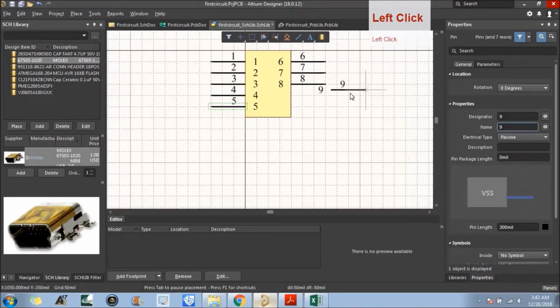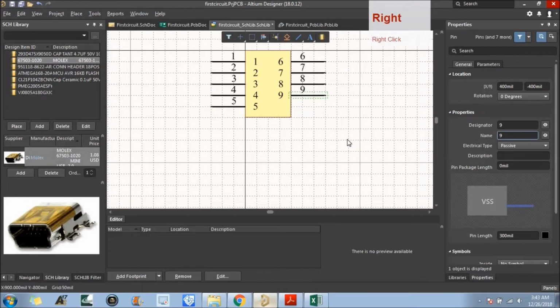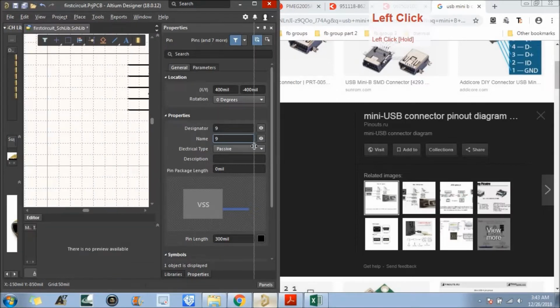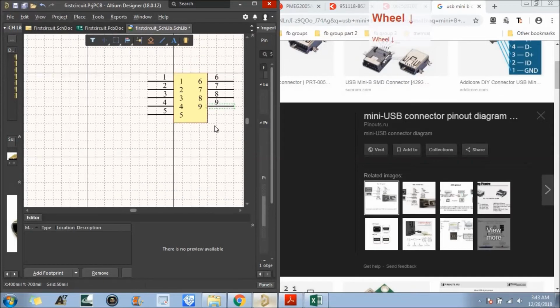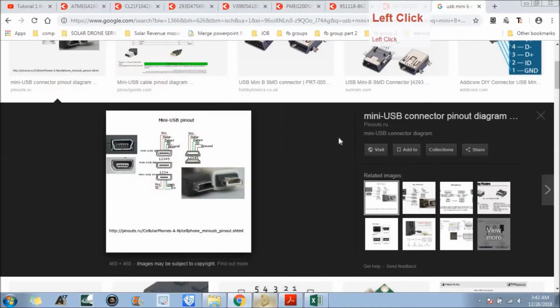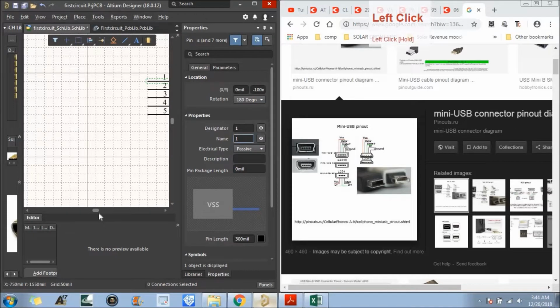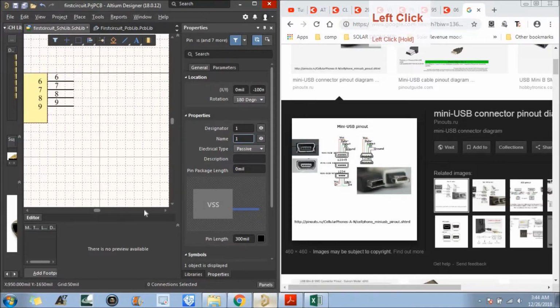Now we can go for the naming. So I'm just split the screen into 2 parts. Okay, just slide this menu a little bit. Okay, so now the symbol is visible. As you can see, the first pin is the VCC. Okay, so I think yeah, I made a mistake there. I need to just widen this particular menu and just slide the symbols a little bit to the left side. Okay, fine. Just change the name to the VCC for the first pin, enter.